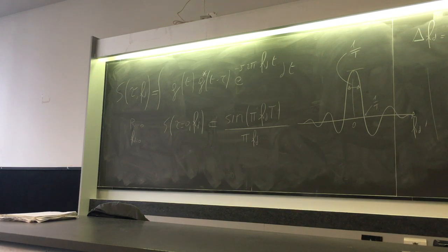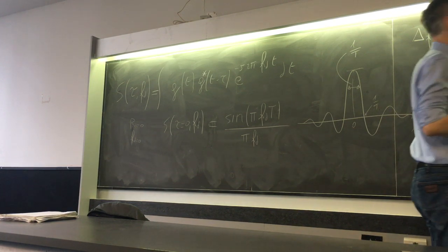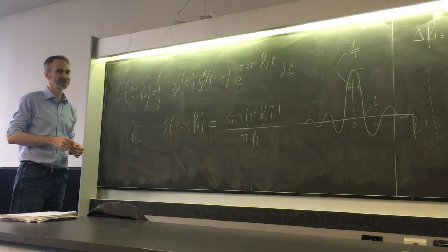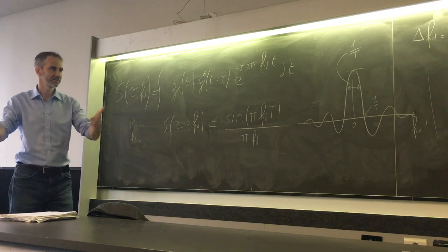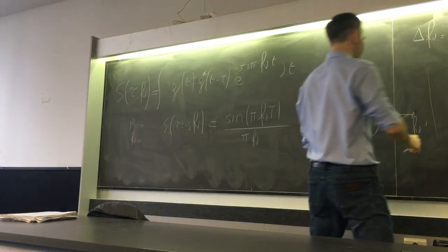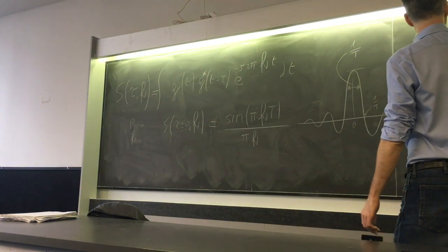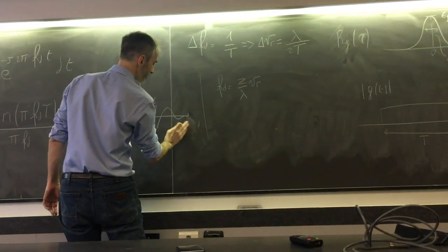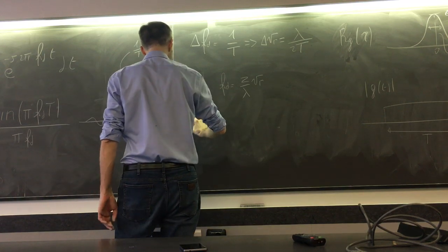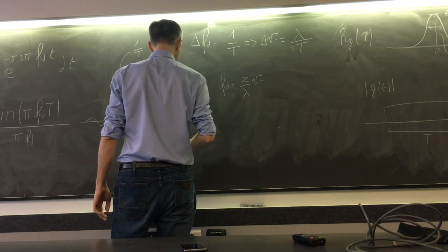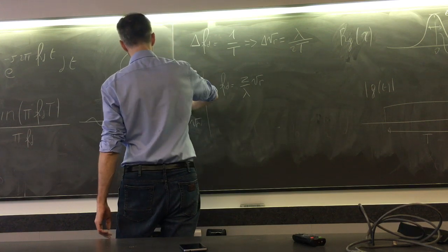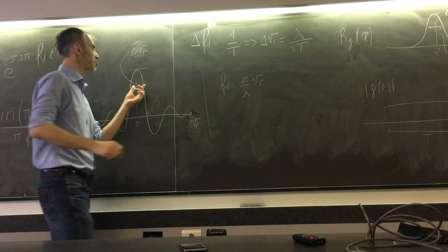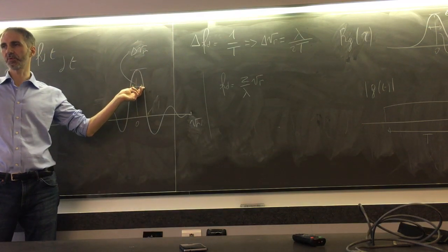Is it meters per second? Yes, meters per second. So it's correct. That is to say, if you just multiply this by half the wavelength, then you can cast this graph directly as a function of the radial velocity, and this is your resolution, so the width of your lobe.